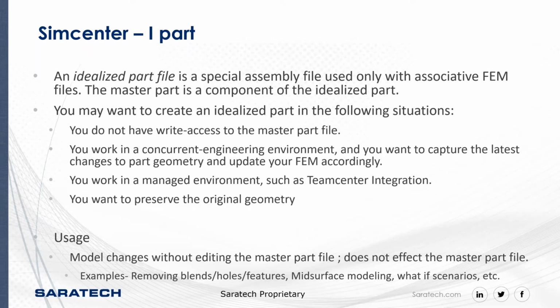It's also important if you're working in managed environments such as Teamcenter, so that if somebody opens up the master part, you can still open up your idealized part. And the important thing here is you want to preserve the original geometry. So normally, if you look at your FEA world and you work on your part and you remove rounds and fillets and things like that, you're physically editing the geometry so you can't go back to where you started. Well, you could if you went backwards, but you're physically editing that geometry. Now, what this will do is it preserves your original geometry as well. So that stays put and you are only editing your local CAE type geometry.